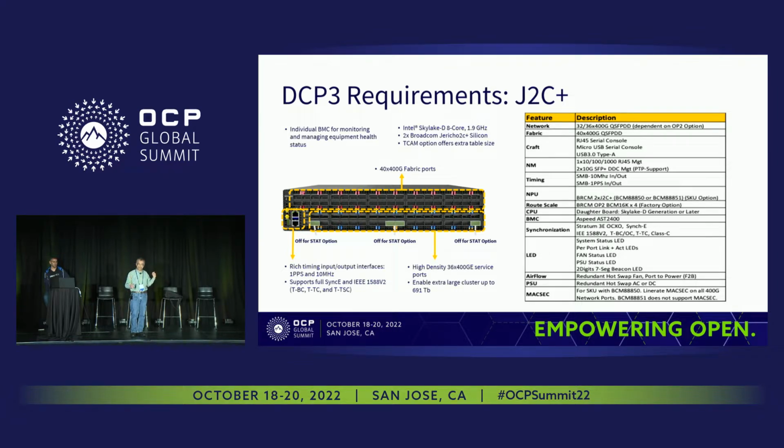We have a dual chip design. Optionally, we can get the OP2, or the knowledge-based processor, for external TCAM caching. If you have a gigantic BGP table or a lot of ACLs, we can do the content addressable lookup. We use 2 chips. The 2 chips, if you believe the math we all did together along with our hardware team, came out to be 36 ports, maximum 48, of 400 gig in a non-blocking architecture.